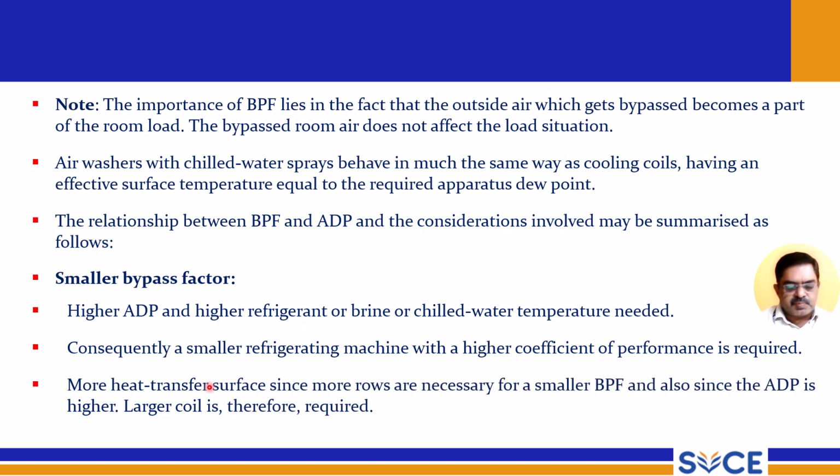More heat transfer surface is required, since more rows are necessary for a smaller BPF, and a larger coil is therefore required.